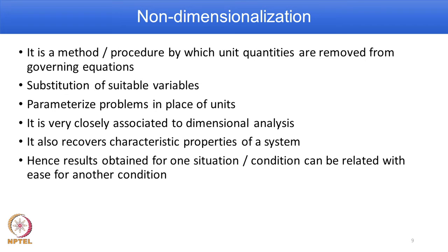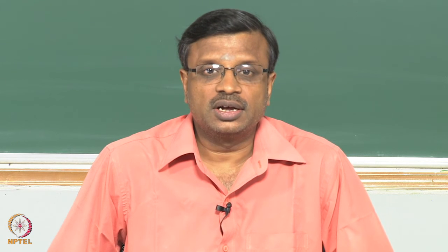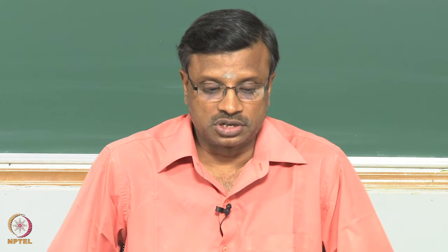The next important topic is non-dimensionalization. What is the meaning of non-dimensionalization? It is a method or procedure by which unit quantities are replaced. So, we have seen three major equations: mass, momentum and energy. In all three equations we also observed there are variables: velocity, density, gravity, viscosity, and temperature. All these variables have units. So, is there a way by which you can remove the units and solve the equations in non-dimensional form? There is a procedure, and that is known as the non-dimensionalization procedure.